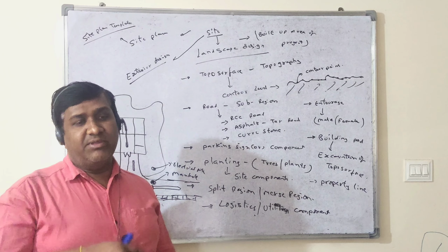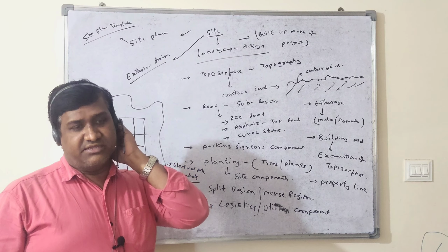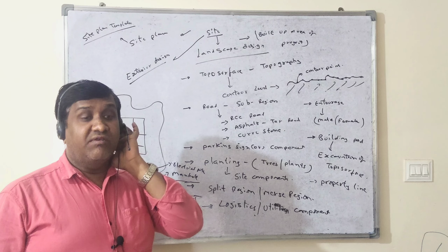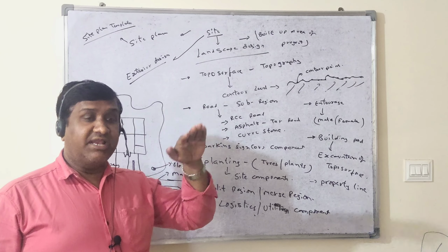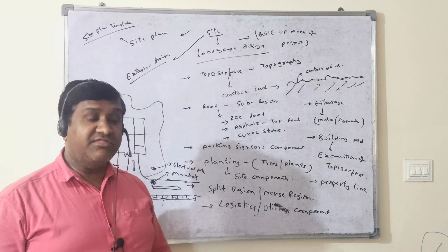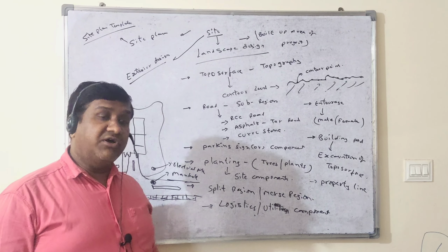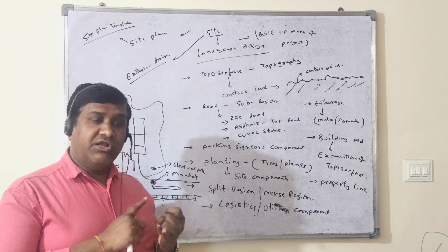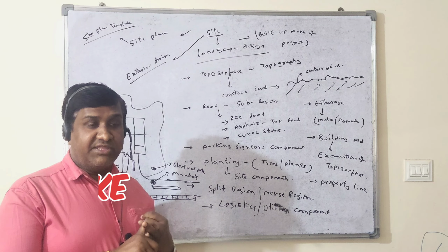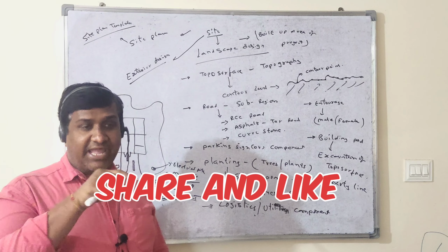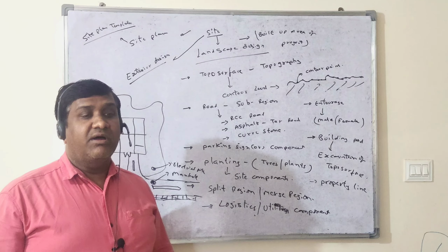In floor plan it will become separately site. You can see that when you take any default template, you will find there is one site, level 1, level 2, and below you can see there is a site plan. That is the site plan. Because while working in a site plan, again you can find the survey point, project base point, and the topo, the X and Y levels.